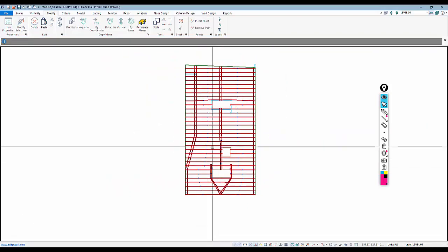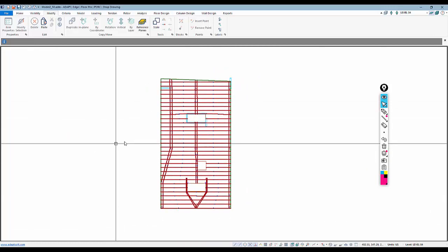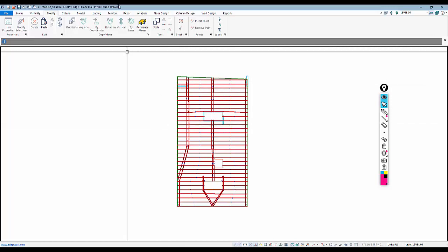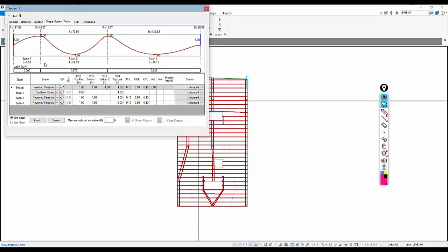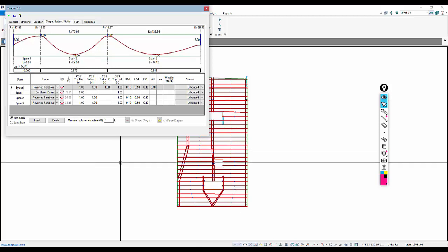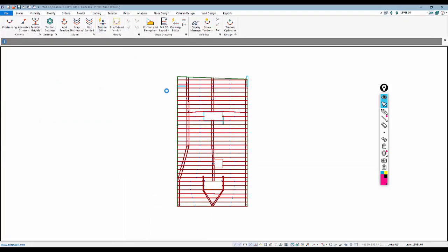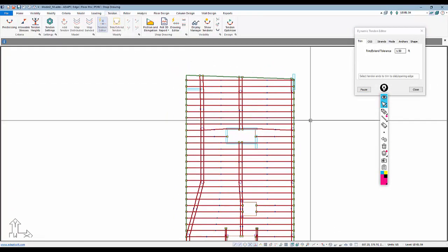Okay, and this finishes out the tendon modeling. Now, in terms of CG, there's a couple of things here to note. Whenever we're editing a tendon, either through the individual tendon property box, remember that the CGs at the top are top down if the anchor is top down, bottom is bottom up in terms of their reference control point. If we go to tendon editor, that's defaulted to the same reference.